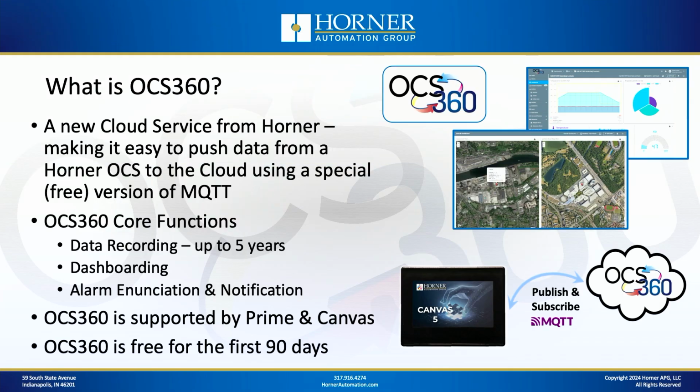Let's get started with our one-slide review of OCS 360, the new cloud service from Horner. It's supported currently by the Canvas and the Prime series, and those controllers can push data to the OCS 360 cloud using a special included and free version of MQTT. Now, OCS 360 as a cloud service currently has three core functions: data recording up to 5 years, dashboarding, and alarm annunciation and notifications. And over the past several weeks, we've shown you how to do all of these things.